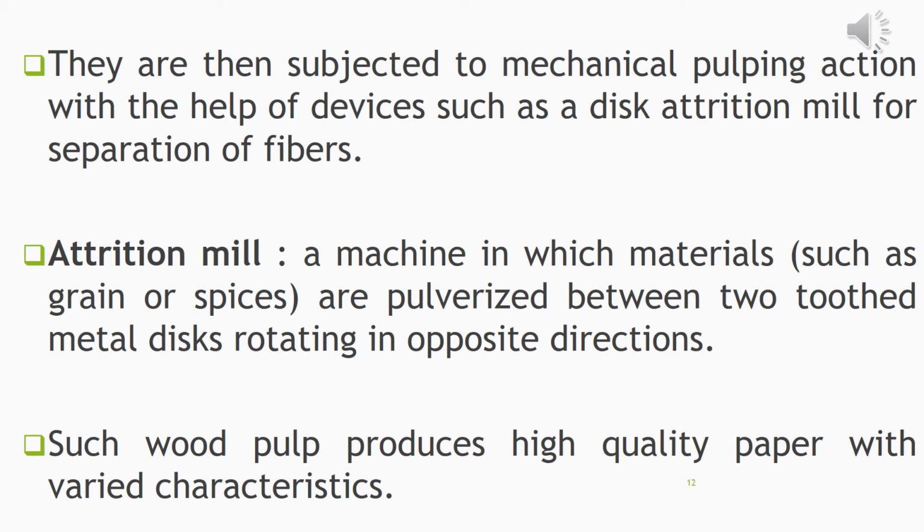After treatment with sodium sulfide combined with alkaline salt solutions, these mildly cooked wood chips are subjected to mechanical pulping with the help of devices such as a disc attrition mill. Why mechanical pulping? They are subjected to mechanical pulping action for the separation of fibers. Now, what is an attrition mill?